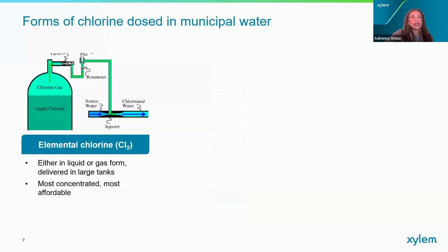Chlorine can be dosed in several forms into municipal water, including in its elemental form of liquid chlorine, also known as chlorine gas, which is available as a compressed gas at 100% strength. The most common ways of adding elemental chlorine to a stream are to feed gas with a vacuum-operated solution feed system or to feed the gas under pressure.